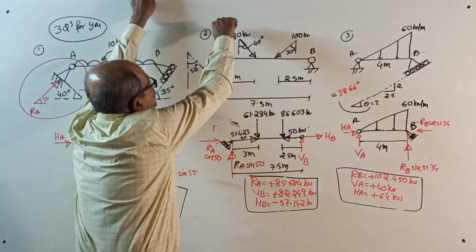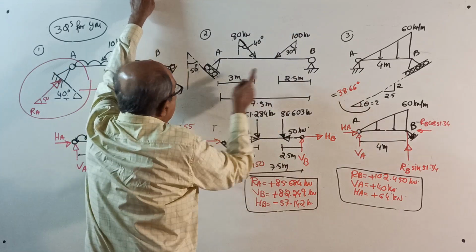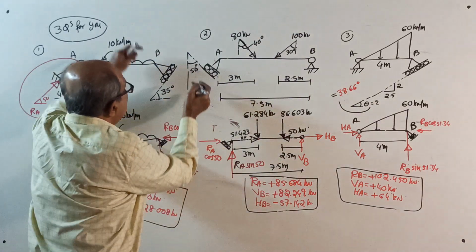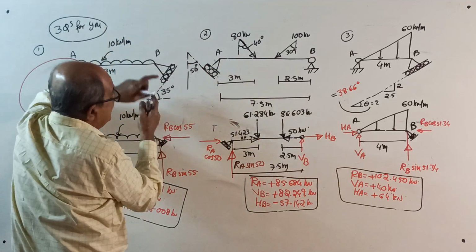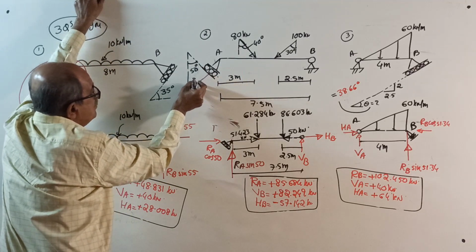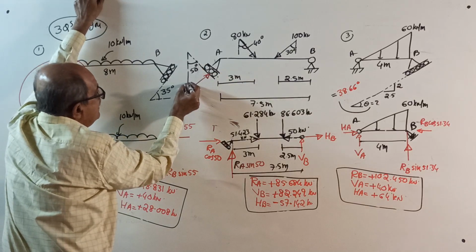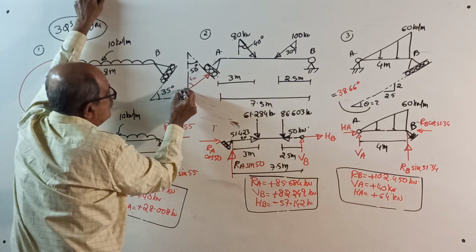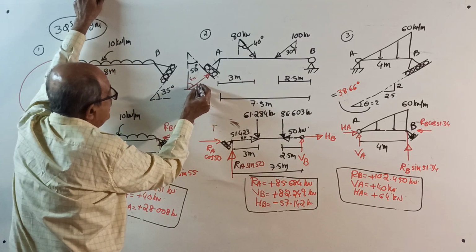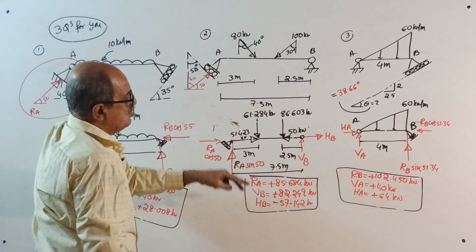Here, two inclined loads are given. Resolve them into components. And the roller is at A now. Remember, this is 50 degrees. Therefore, be careful. First you write the question. Later, when you put the normal reaction, if that is 50, this will be 40. So with the horizontal, it will be once again 50 degrees only. Be careful. Now you can solve the question very easily.